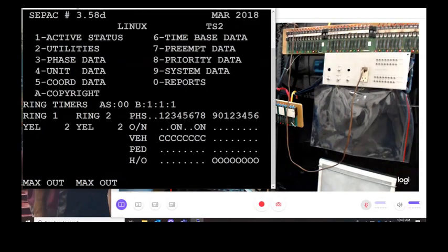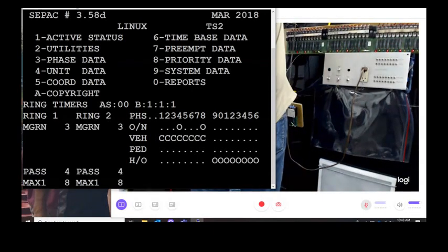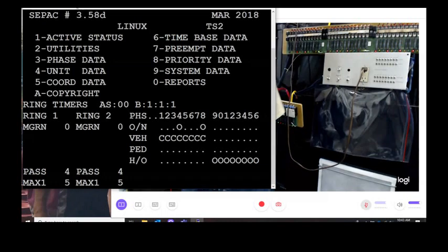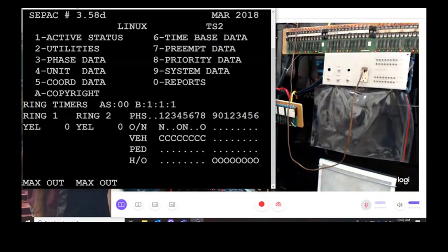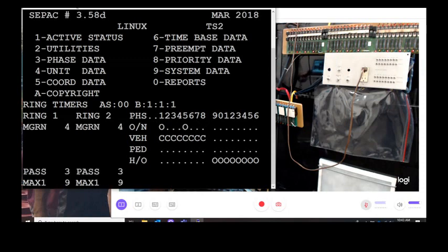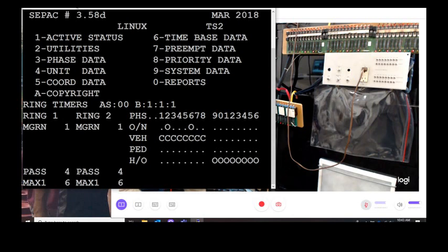All right, so I'm going to create a conflict. This is the way: when we build every cabinet, we do a conflict monitor test to make sure that we have all the jumpers right, our compatibilities are right, and it creates the fault, and then we print out a report so that we have it from somewhat of a liability standpoint. For those of you that do final inspections, there's some consultants that actually have you do the conflict monitor test in the street. Obviously, you have a police officer out there